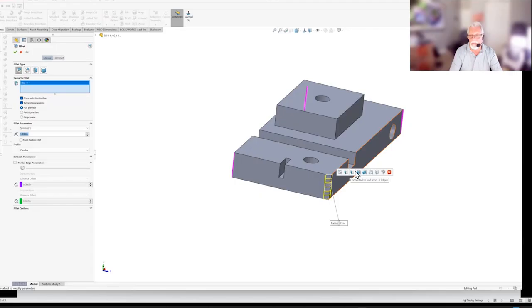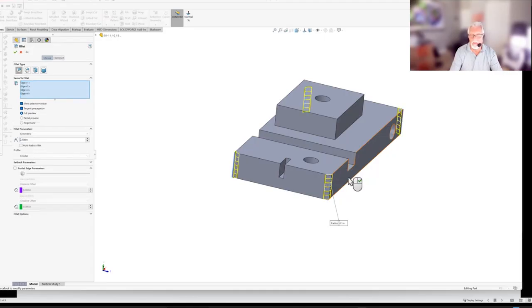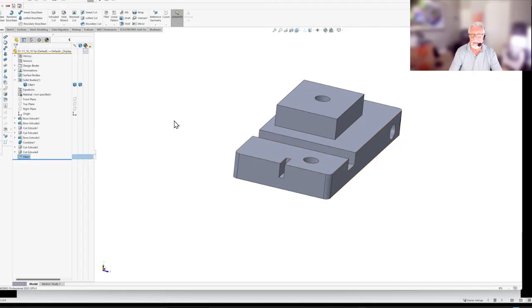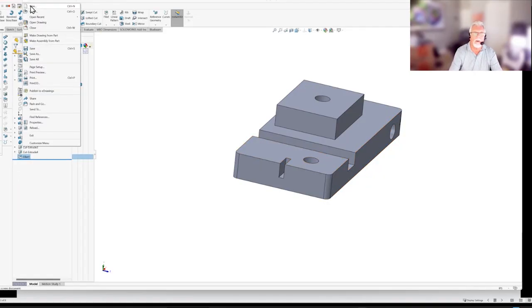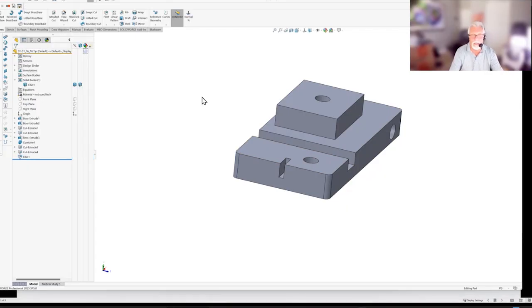It's going to tell me all the different combinations of putting those edges on this part. So if I want all edges broken with that, if I want similar edges, and what it's looking for on a face, the outside edges, the 4 is what I want. So there's a lot there, and sometimes maybe you move your cursor too fast and you lose it. So now let's go back into our assembly, and I'm going to hit my R key again.